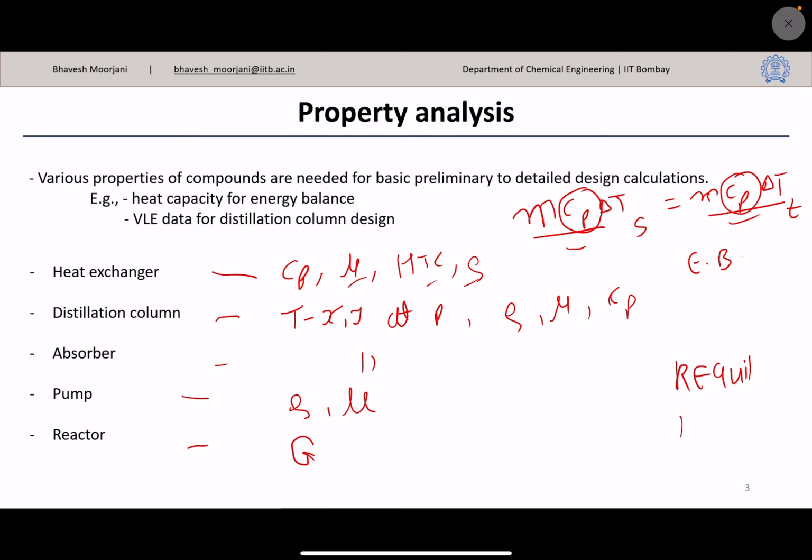So similarly, we have this RGibbs model available in the reactor model palette. So what does RGibbs do? It does the Gibbs free energy calculation, and the lowest chemical potential, or the Gibbs free energy, will give you the maximum equilibrium composition that can be achieved.